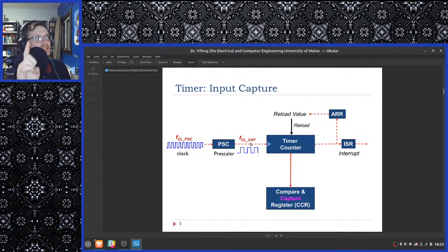The only thing the CPU may be required to do occasionally is set the value in ARR, or read or write the value in CCR and receive interrupt signals. Those are all just load store operations.